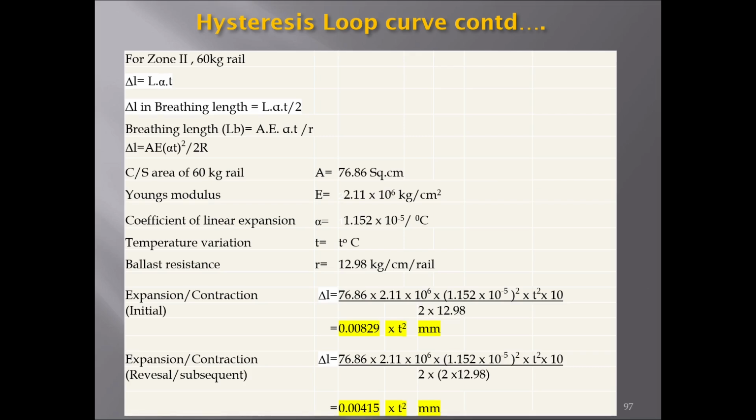With this I want to work out the gaps for various rail temperatures and plot them, to show how our system will look, how we pick up the maximum expansion or contraction at a particular temperature, and how we compute the range of gaps for different temperatures. We can then compare with the table given.